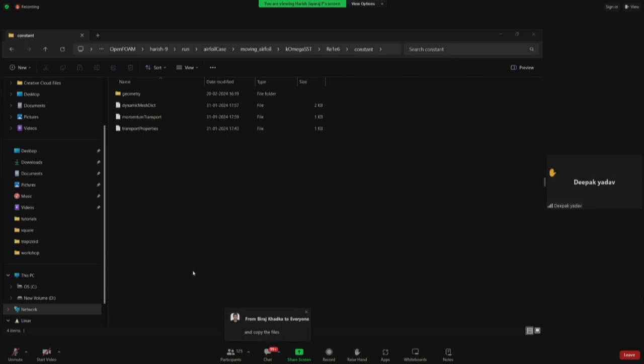Hello. Yes. What is the role of Y plus in meshing? Actually, if Y plus is less than 5, then the layer is in the viscous sublayer, and if the Y plus value lies between 5 to 30, that is the buffer layer. That explanation is beyond the scope of this tutorial. So we cannot be explaining Y plus right now because we have to do 2 turbulence models and sort out the bugs. So please check out the documentation and see how Y plus influences the simulation. That is beyond the scope of this tutorial. So kindly read through the documentation. Thank you so much.